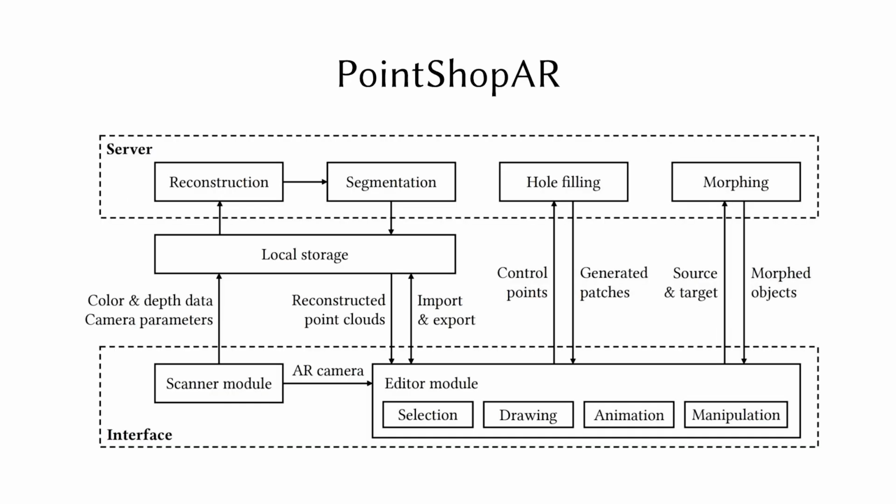We then developed PointShopAR, a novel tablet-based AR system that supports environmental design prototyping using point cloud instead of 3D models and integrates capture and editing in a single application. The interface is implemented using Apple's ARKit and runs on an iPad with a scanner module and an editor module. We also run a lightweight server on a laptop, implemented using Python and Open3D to process point cloud reconstruction, segmentation, hole filling, and morphing.